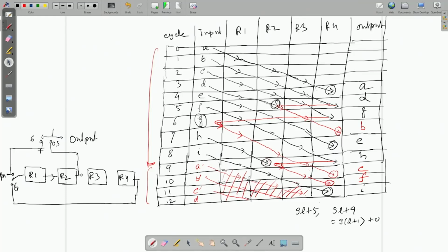It is a modulo notation. So if I follow modulo notation, it is actually 9L plus 9, but you can also write it this way. 9 means 0 to 8, those are the system cycles for one input clock. 9 means I am entering the 0th system cycle of the next input clock, L plus 1th. That is why we write 0 here. That is the style followed by Parhi and others.